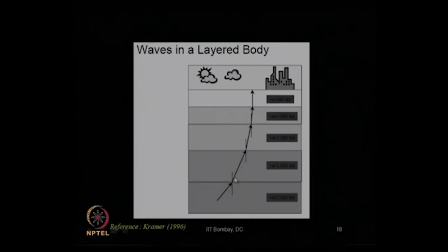So, that is the reason as we go from the bottommost stiffer strata to the softer strata close to the ground surface, the rays keep on moving towards the vertical, and close to the ground surface they will almost become vertical. So, that is the reason why in our geotechnical earthquake engineering problems for civil engineering designs, we consider all seismic waves close to the ground surface to be vertical in nature.